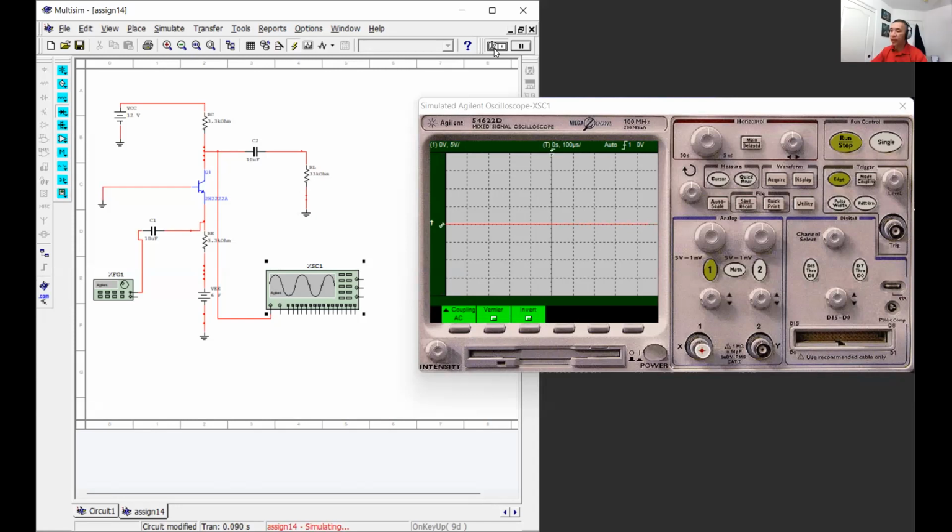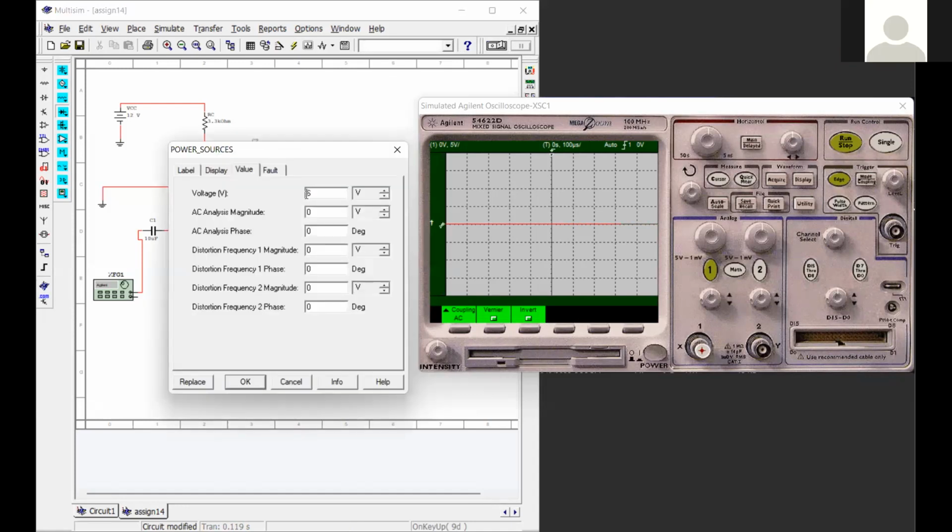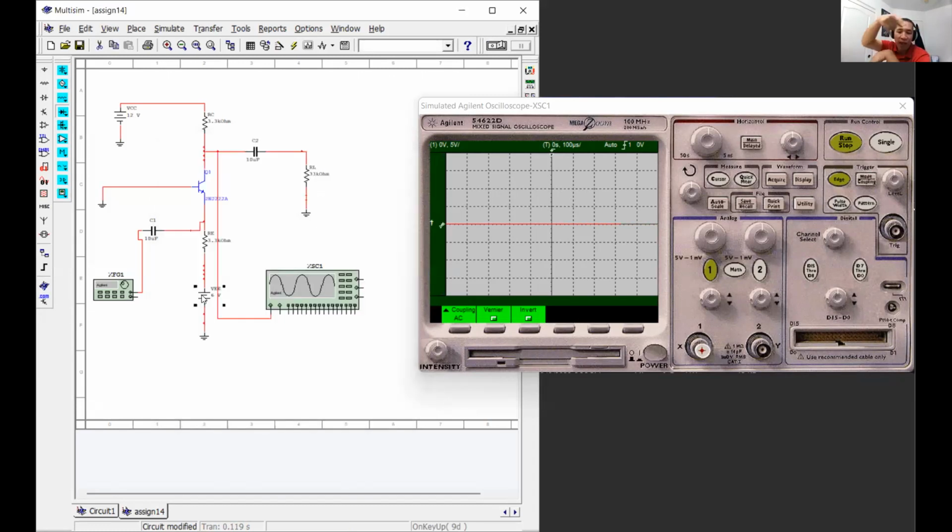Okay, yeah, your VEE should be the negative. It should be pointing to the top. Can you see it on the bottom? Your VEE should be negative, -6. Okay, what you want to do is go ahead and remove the wire there, and you have to rotate that. So you have to remove that wire right there at VEE. Go ahead and disconnect all those wires that are connected between the ground and that component. And then after that, we have to rotate that component.